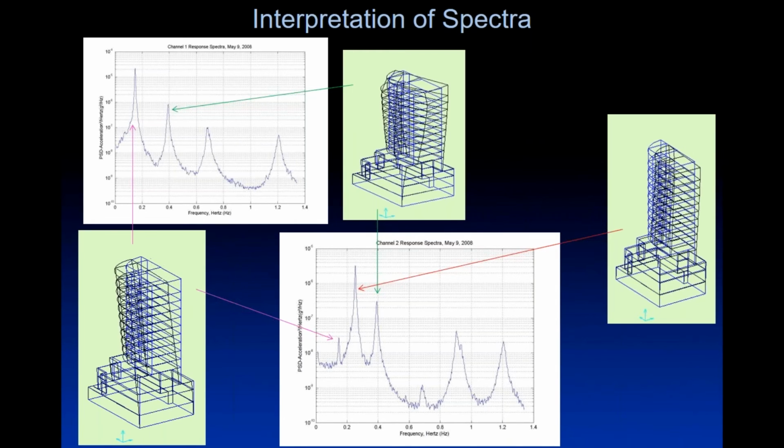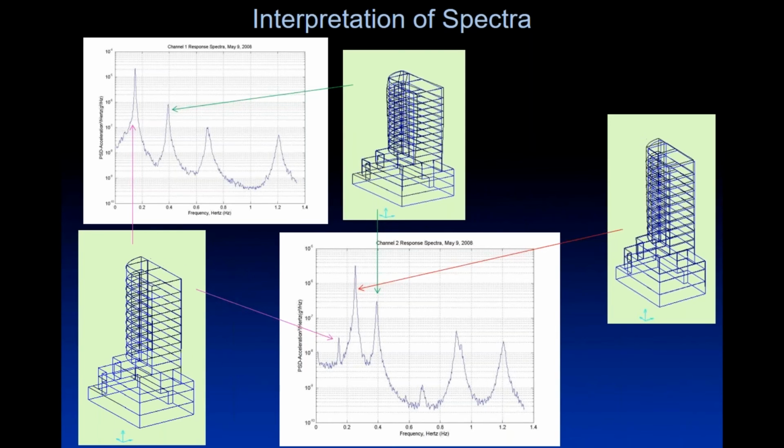You don't need to monitor for so long when you've got a reference and a traveler, because you just compare the 2 signals and you look at the ratio and the phase between them. This is what I'm talking about here. What we've got is sway of a structure under a force, and we're doing spectrum analysis. So we've got frequency along here, which is the inverse of period. And we've got the amplitude on a logarithmic scale. This is from a real structure in the field.